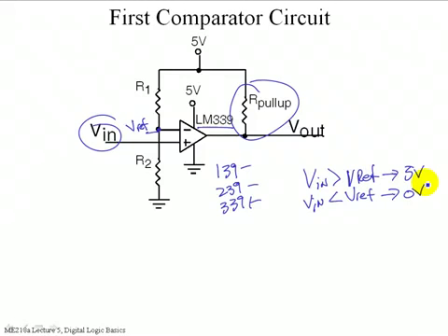Do the golden rules of op amps apply to comparators? That's a good question. Anybody? You say no? Well, one of the golden rules of op amps is that the two inputs, positive and negative, are equal, right? I mean, if that were true here, it would be. Okay. So that brings up an excellent point. We have a golden rule that says the inputs are at the same potential. There's a requirement on that golden rule that you seem to have forgotten.